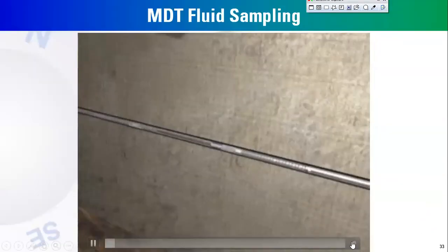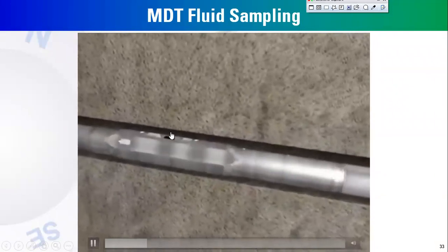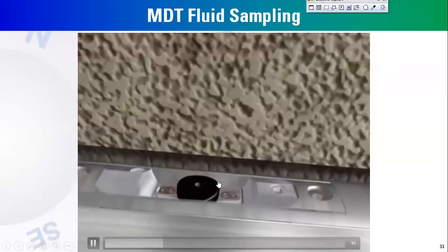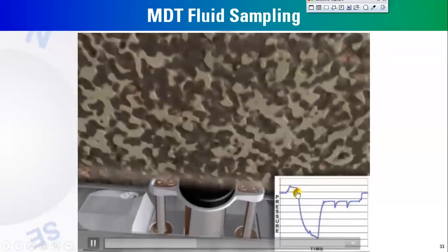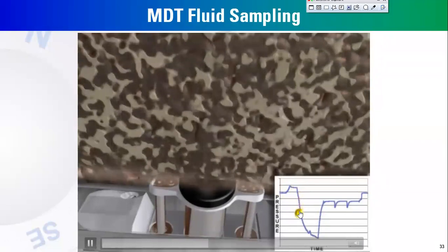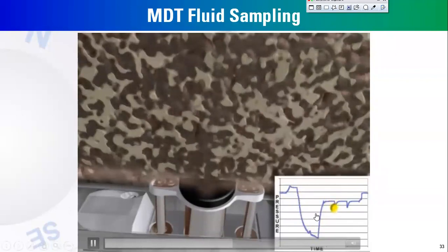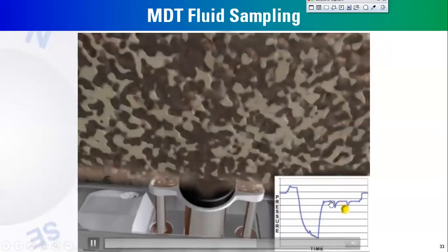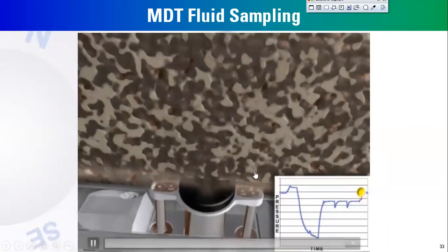So in this video, as you can see, the process of bottom hole sampling, this is the wireline tool. Let's say this is the depth of the selected sampling point. This is the probe. Once the packer is set, we can collect samples, start drawdown. The pressure is declining, as you can see. While pumping out, we can stop pumping to measure reservoir pressure, and then we can collect the sample after the sequence and the process of pumping out.